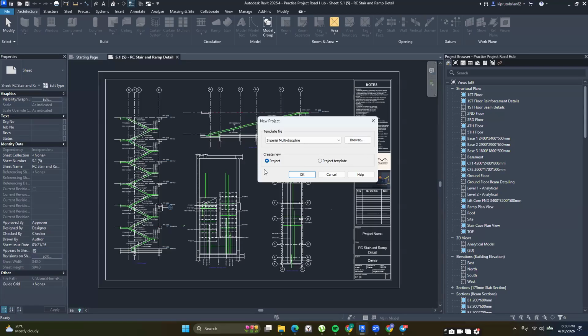I'd recommend you create a template from a project that you've already worked on, so that you can see the changes in real time. So that if you make a change to a grid, you can understand what the repercussions of making that change are, and once that change is sufficient for you, then you can have it in your template.